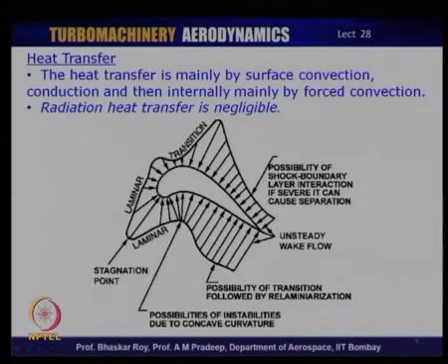So, the stagnation point is indeed the hot spot, the hottest spot on the blade surface. As the gas picks up speed, it actually drops off the temperature, and then through the transition from laminar to turbulent flow, as it flows over the blade surface, the gas actually accelerates. As it accelerates, the local temperature, the static temperature remember, is the temperature that the blade would indeed be feeling. So, the local static temperature starts falling off. So, as you have expansion or acceleration over the blade surface, the static temperature indeed falls off.